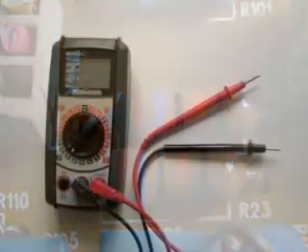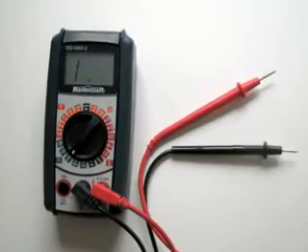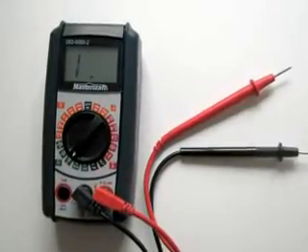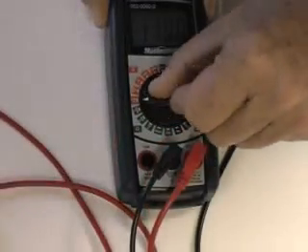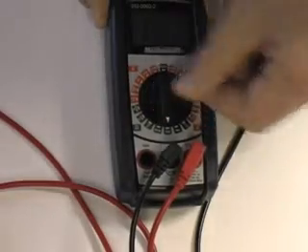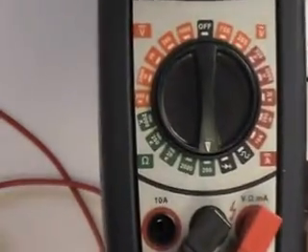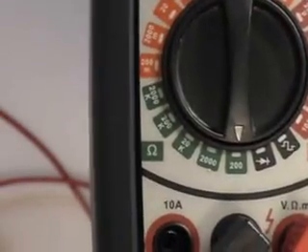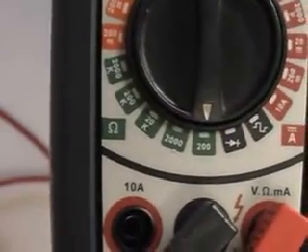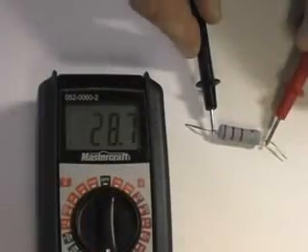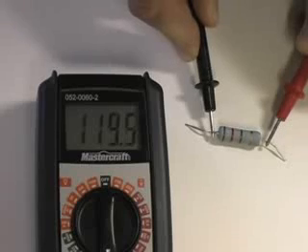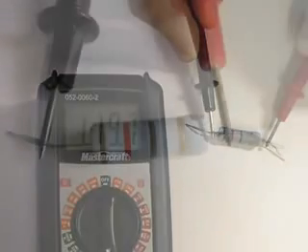You can use a digital multimeter to directly measure the value of a resistor. Set the meter to measure resistance. Depending on your meter, you may have to select a range. For this example, I have chosen a range of 0 to 200 ohms. Once set, then touch the probes to each end of the resistor. The measured value is often slightly different from the value indicated by the color code.